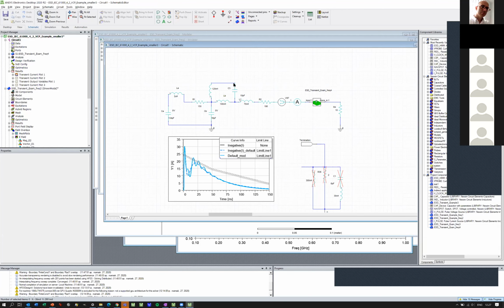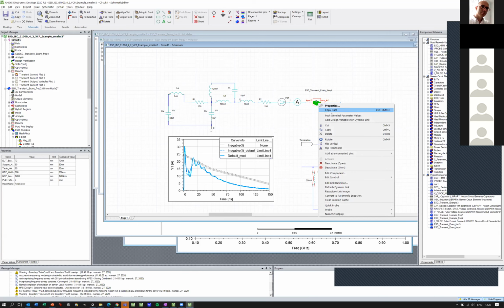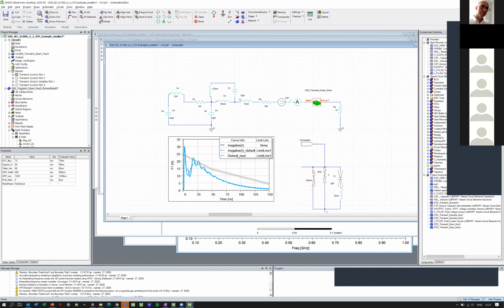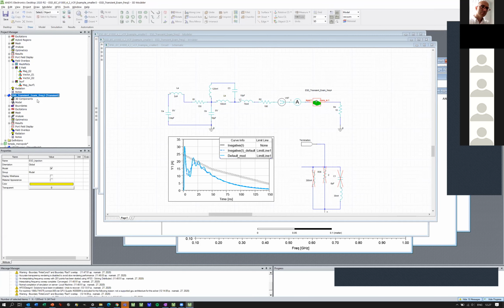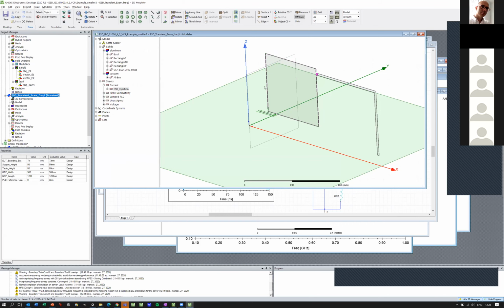This is my source circuit, and it's pushing this time domain curve into my radiation plate, and then I go here and push the excitation data back to the 3D, and then I can plot the magnitude in time domain in this setup.